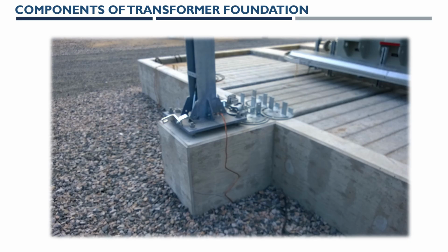So here you can see a closer view of the precast concrete grating, having gaps of nearly 10 mm to 20 mm, where the oil can be spilled inside the bund wall area. So this is laid just below the transformer, having 100 mm or 50 mm edges, and all this is usually supported on the transformer bund wall itself by making a shape of L.